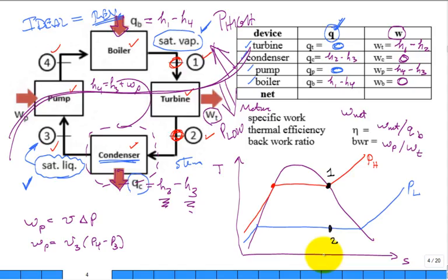Okay. Now, what comes out of the condenser, state 3? Where is state 3? Some people are stopping state 3 right there. Is that the place to stop state 3? Where is the place to stop? Way over there. It's at that saturated liquid low pressure.